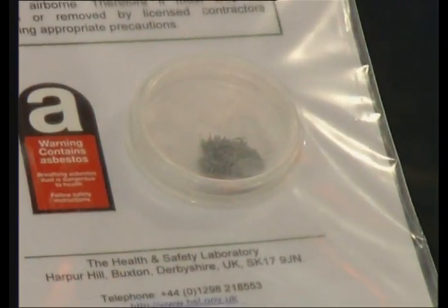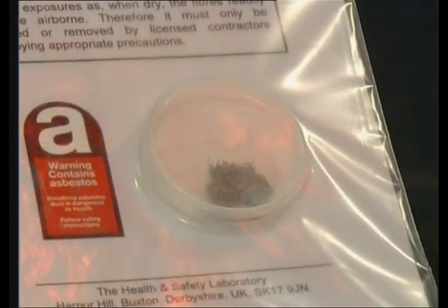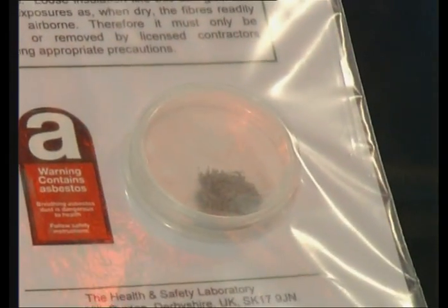And to the layman, it's almost impossible, really, to tell the difference between the 3 types of asbestos, isn't it? That's right. The colours actually refer to the asbestos in its raw mineral state, but once it's been put into products for commercial use, then it's very difficult to tell the difference. I've got some examples here that you can see. This is blue asbestos, which is sort of grey in this instance, and this is a fairly pure type, which would have been used for insulation. And fairly rare now, it has not been in use for some time. And again, we have to remind ourselves, it wouldn't necessarily look like that anyway, but that's its raw state.